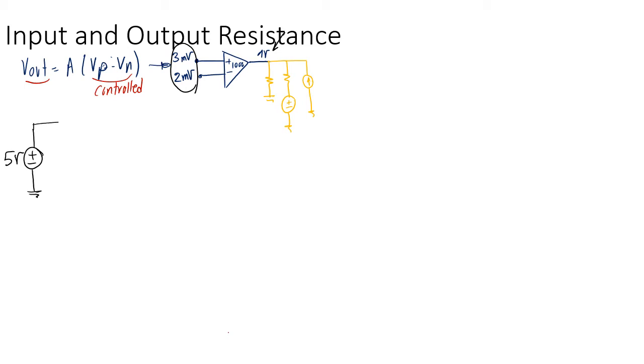So if I connect this voltage source to, let's say, a 10 ohm resistor, it doesn't really matter which, you know immediately that if I define these two points as ground, here is always 5 volts, right? Why? Because I have a voltage source there. So this is basically an ideal voltage source.